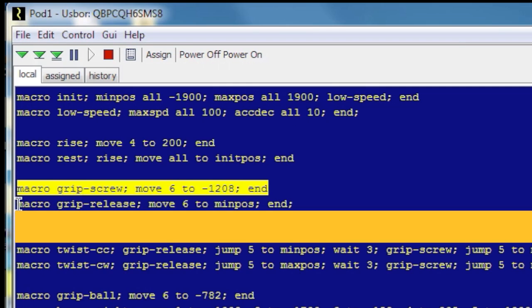Find ABSI now. Got it? Okay. And by the way, ABSI stands for the absolute value of the servo current. Current is usually denoted by the letter I, so ABS-I or just ABSI. In our case, ABSI generally corresponds to the torque or rotational force the servo is exerting.